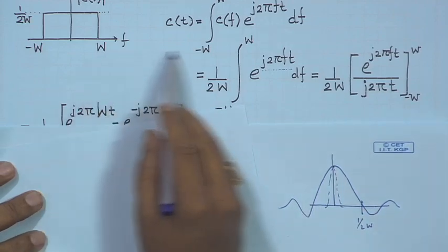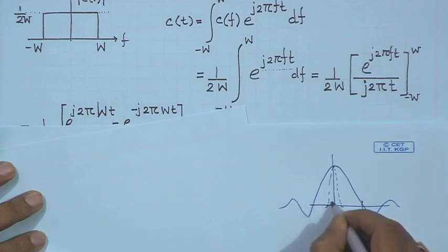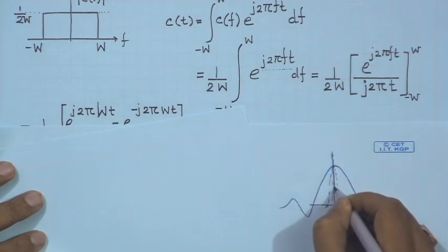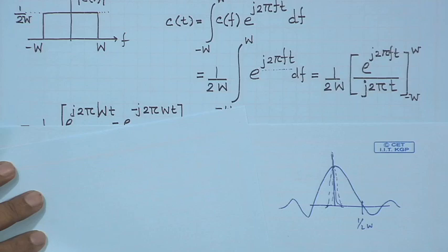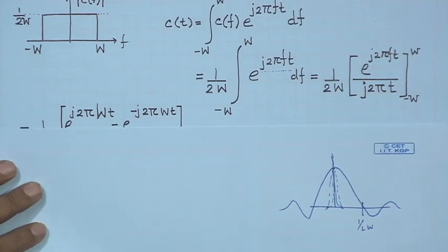As you make W tend to infinity, this will approximate an impulse, which matches with our typical understanding. If W is infinite, which is usually the case of the AWGN channel, that is how we generally start, so the impulse response is ideal: the impulse in produces an impulse out.